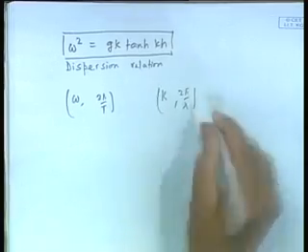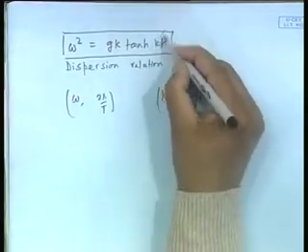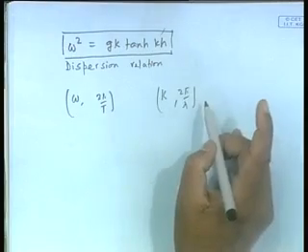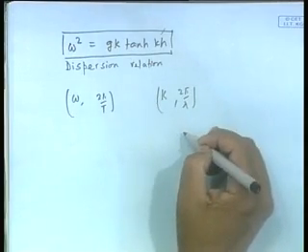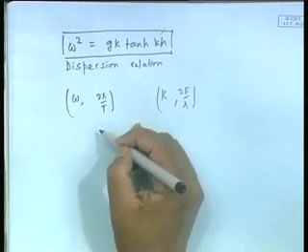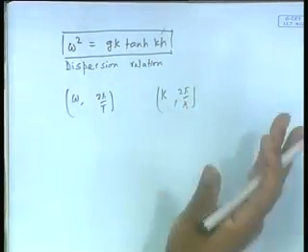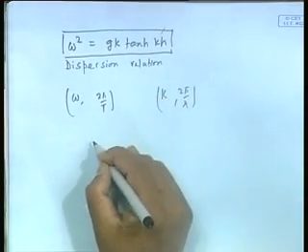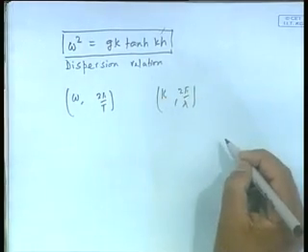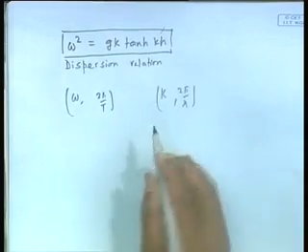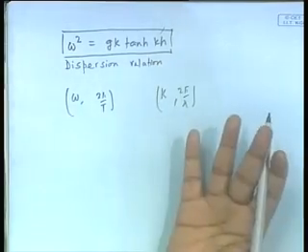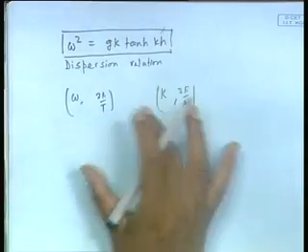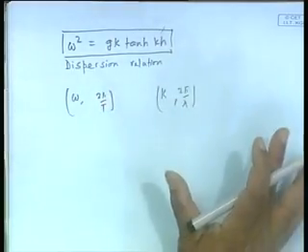That means essentially if for a given water depth h, which means that if for a given water depth I have a wavelength lambda, it is necessarily of certain period t. I cannot have, for example, in a given water depth a wave period of 10 second and 20 second of same length. Now this you can contrast, for example, with electromagnetic radiation, where you can have different wavelength, different frequency, but there is a speed is constant.